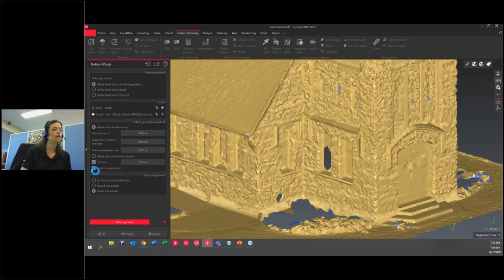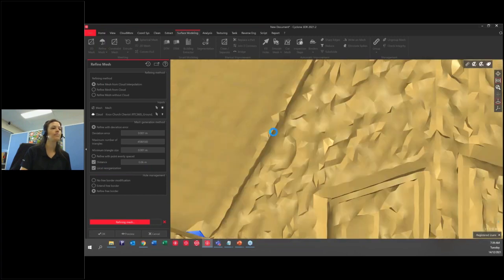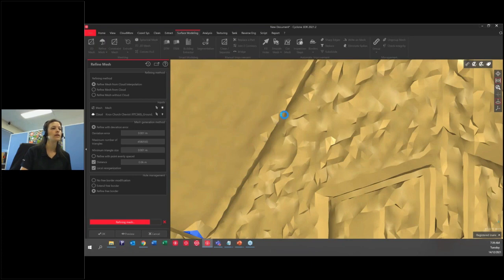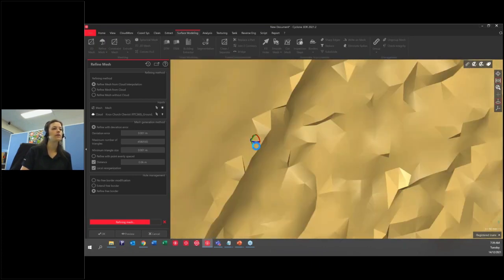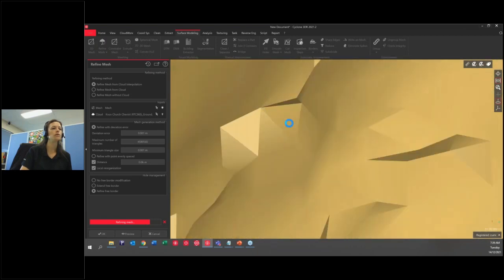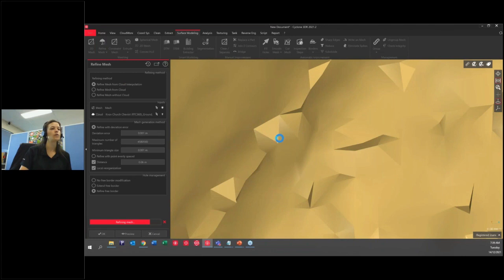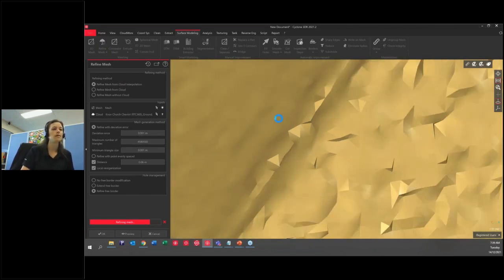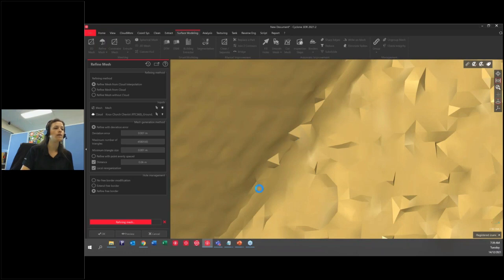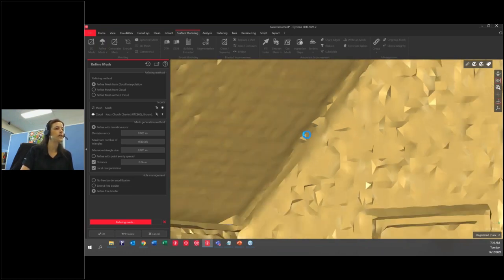This is always ticked. I don't even think of a time where you wouldn't want to use it, I have to say. It should probably even be hidden, but it's nice to have it because we can explain. What we're seeing here is that on the edge, those triangles are just regular, they don't really have any knowledge of the real shape there. These triangles, for example, with these 4 points, you'd actually want them to be triangulated, or maybe here, triangulated in this orientation instead of triangulated over the edge. At the moment it's like that because it's a regular mesh, so the triangles are as equilateral as possible. But with the reorganization, that's actually going to change the way the triangles are organized so that it will position them nicely along the curves and edges.